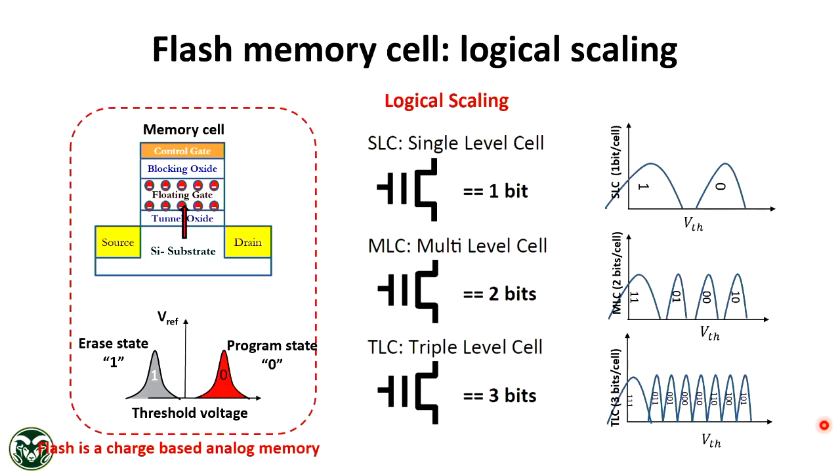More voltage. Because already you are using a charge pump, amplifying the voltage to 20 volt. The highest VT level will be around 7 volt, maximum you can go. So if you want to go for 10 volt VT, you need to really increase your charge pump strength a lot to amplify the voltage.